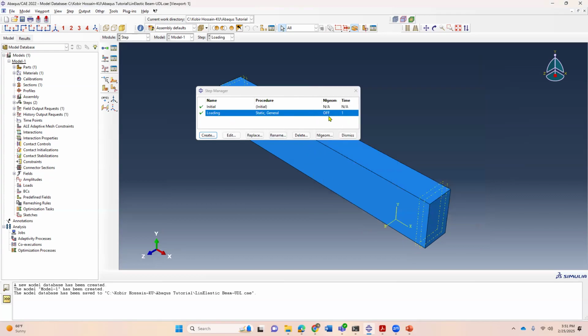We click on OK. Oh, so we could change the nonlinear geometry option. So we definitely want it. So we had to change this one. Let's keep the nonlinear geometry part on, so that when your beam deforms, if the geometry changes, it will change its nodal position, right? So we want that nonlinear geometry to be included in the analysis.